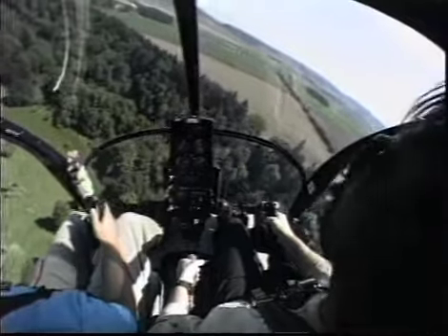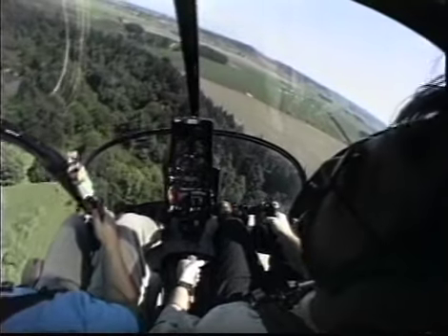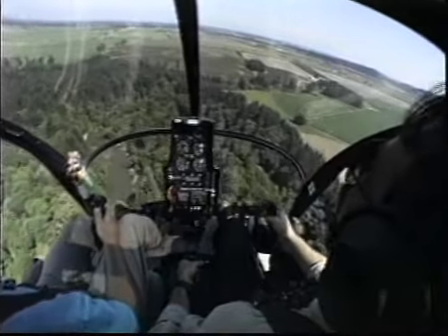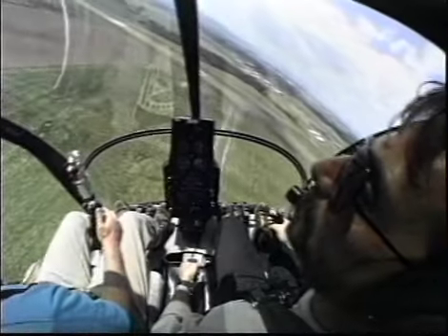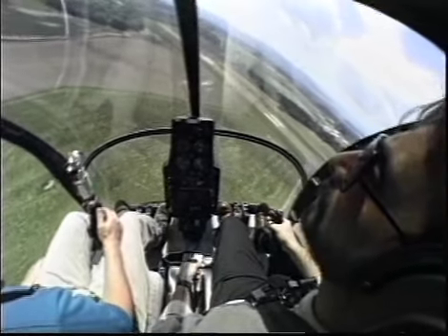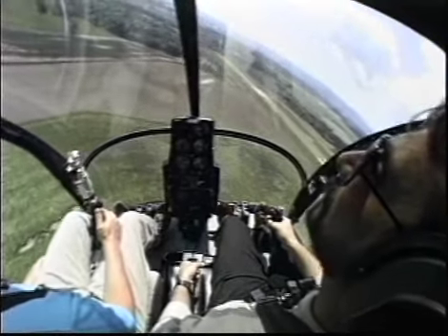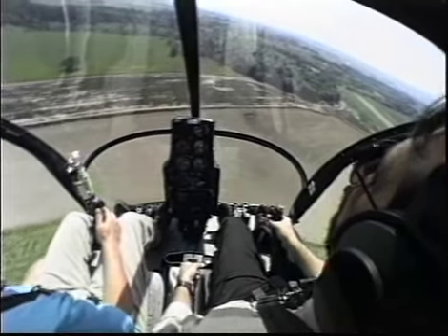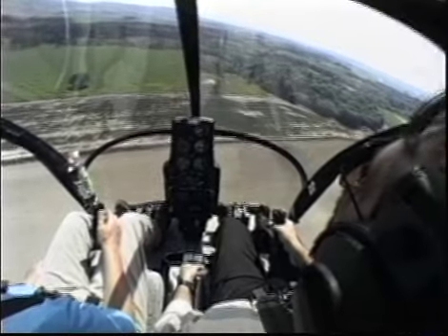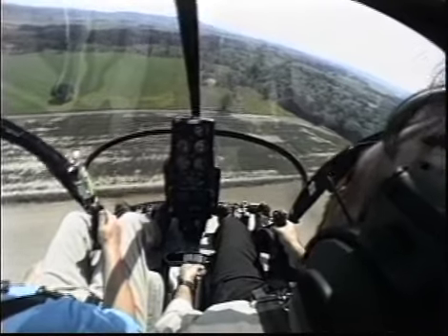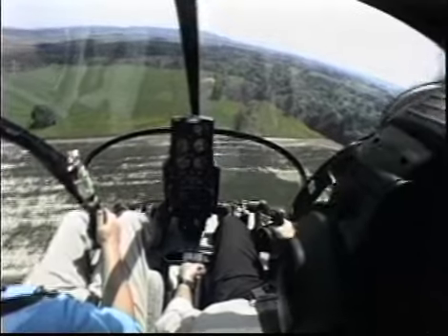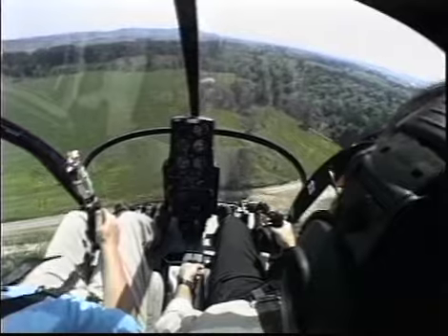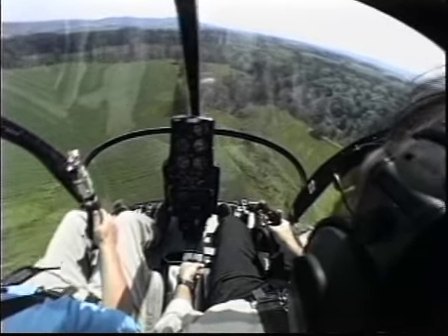This includes determining wind direction and speed, estimating the type and height of obstructions, and assessing other potential hazards. If the high recon suggests that the area is suitable, you should then fly a practice approach to the landing area. Use this low reconnaissance to verify the information gathered in the high reconnaissance. If everything still looks good on the low recon, simply continue in on final approach. However, if the situation all of a sudden presents new difficulties, execute a go-around from the low recon immediately.